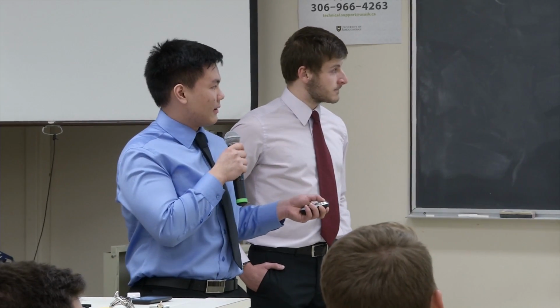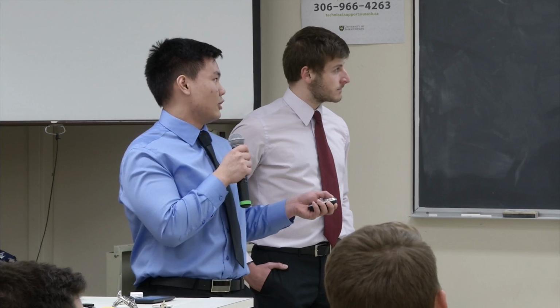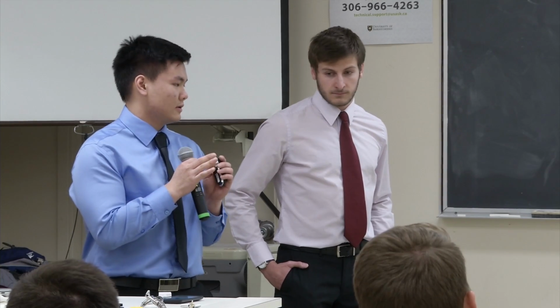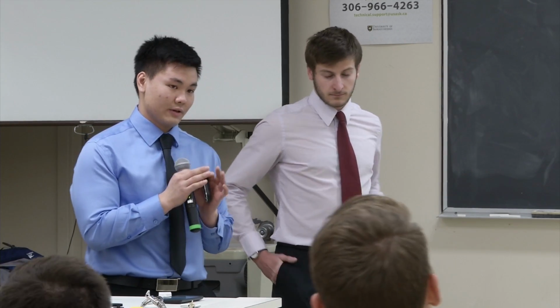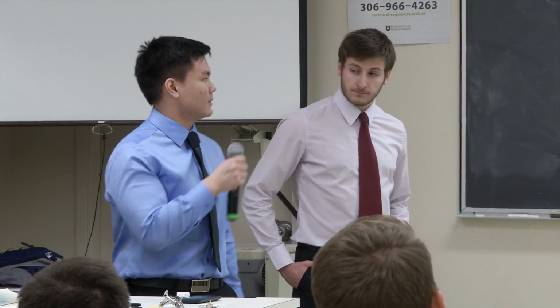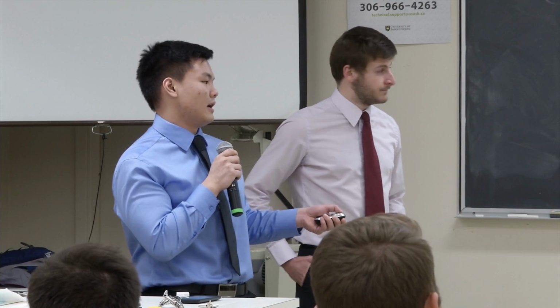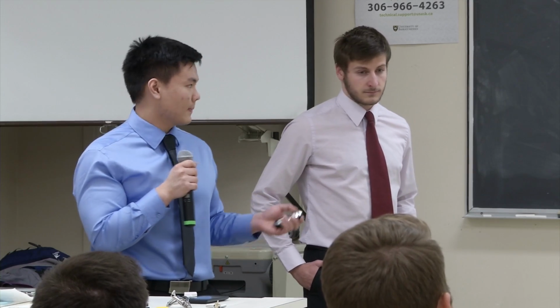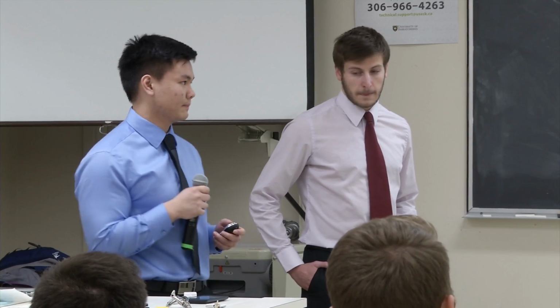As you can see, details such as the slope of the reading as the object is being put down are different. The duration of the force sensor reading going down is longer compared to the slip sensors, where the slope is very steep. And using analysis such as a discrete time derivative, which basically tells us what the change in the sensor readings is at the time, we can help identify what slip is, how we can characterize it, and be able to adapt to slip.